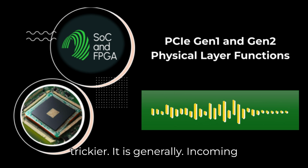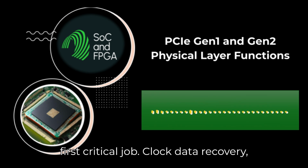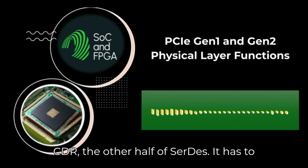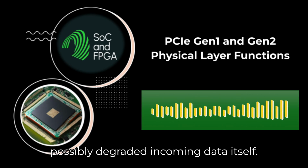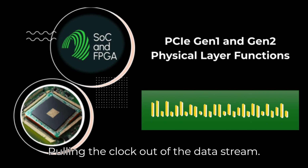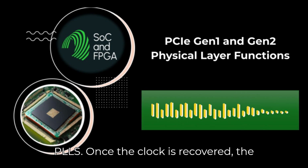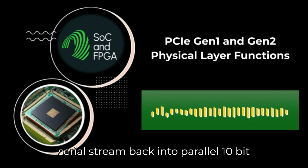Sounds trickier. It is, generally. The incoming signal hits the differential receiver. First critical job: clock data recovery, CDR, the other half of SerDes. It has to figure out the timing from the noisy, possibly degraded incoming data itself. Pulling the clock out of the data stream? Wow. Yeah, it's clever stuff, often using PLLs. Once the clock is recovered, the deserializer uses it to convert the serial stream back into parallel 10-bit symbols.